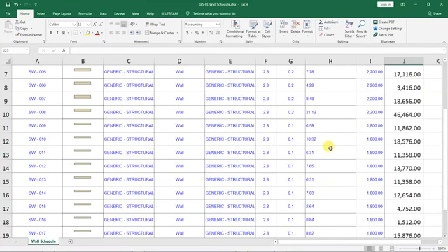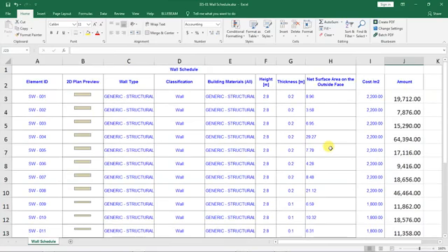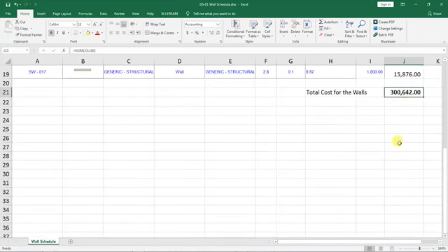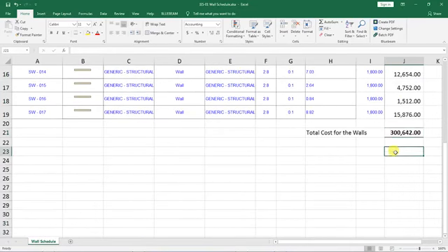What we've done is we have just extracted the data right from Archicad, filtered it, then exported it to Microsoft Excel. Then opening that file in Excel, we have added some columns for cost per square meter and the amount, and then we've done basic formulas of multiplication. Then at the end of it, we've made a summation, and this is just very easy, and I hope you've learned something from this. It's not the only way of doing it. There are other advanced ways, and if you've been experimenting with Archicad BIM data and how to export it, I want to know, so leave a comment in the comment section below. I'll be glad to know what you've been working on lately.